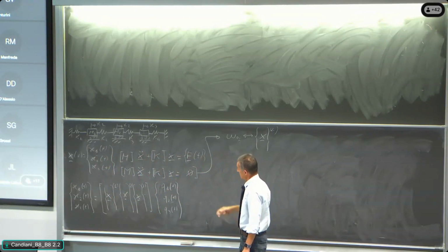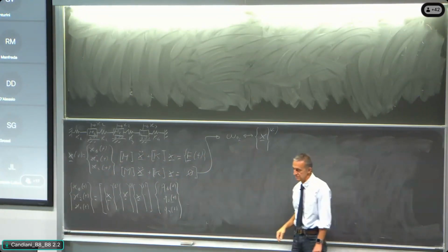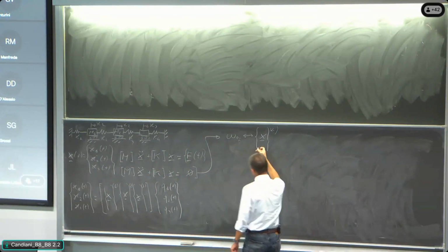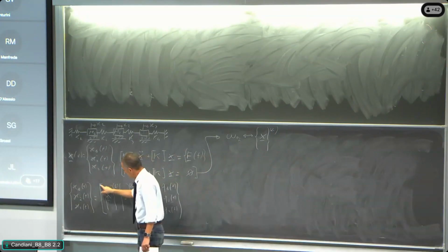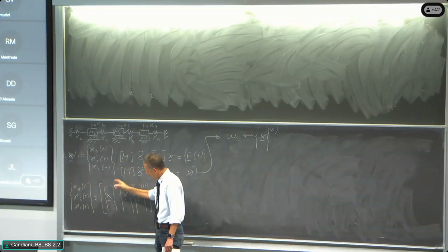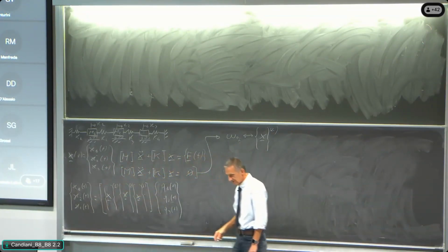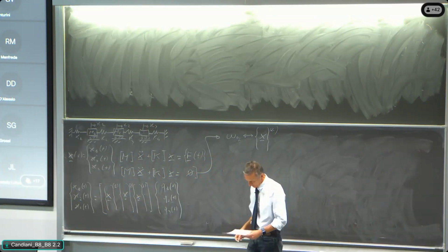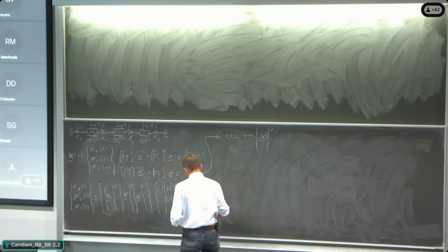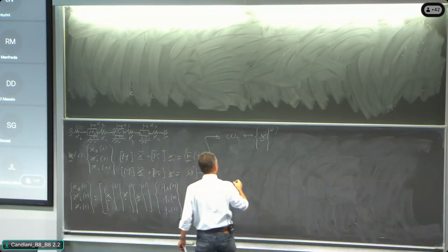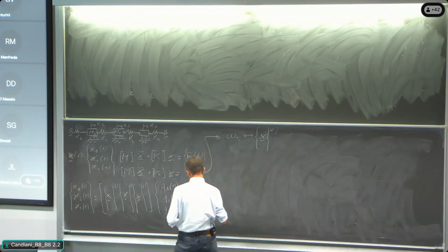And then we can study the forced motion and the free motion. Studying the free motion, we study eigenvalues and eigenvectors, natural frequencies and eigenvectors. With the eigenvectors, we build a transformation matrix, the matrix with each eigenvector positioned by columns like that. This transformation matrix, that we call phi, is what is defining the transformation in principal coordinates.